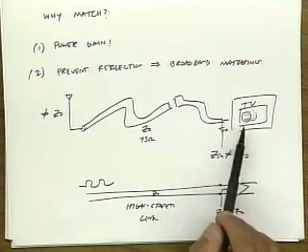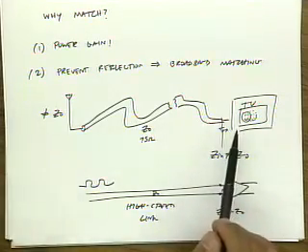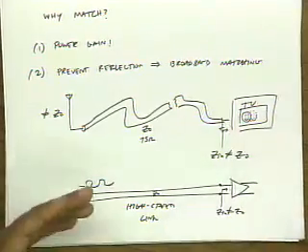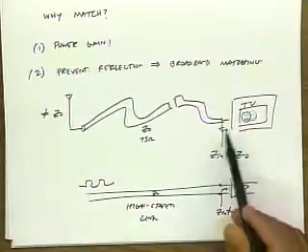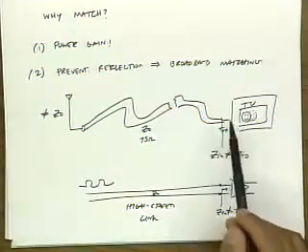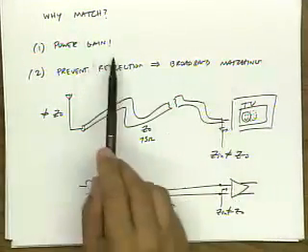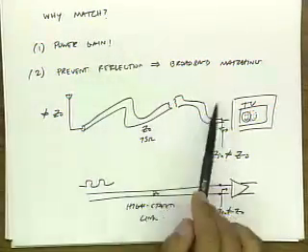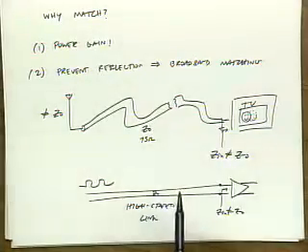Whereas for the television signal, if we're just watching one channel, we could stand a narrowband match. But if you want all your television channels to look equally good, you want a broadband match. So there are cases where we just care about one frequency, like maximizing the gain of a narrowband amplifier, and other cases where we'd like a broadband match.